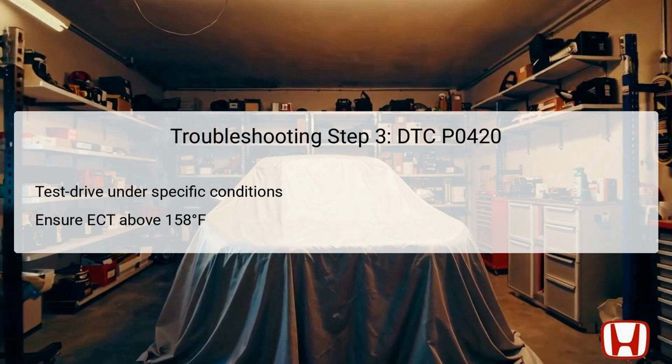In Step 4, you'll monitor the onboard diagnostic (OBD) status for DTC P0420 using the HDS. Depending on the results, if the HDS indicates that the system has failed, you'll proceed to the next step in the troubleshooting protocol. However, if the system indicates passed, it suggests that the issue might be intermittent or that the system is functioning properly at this time.